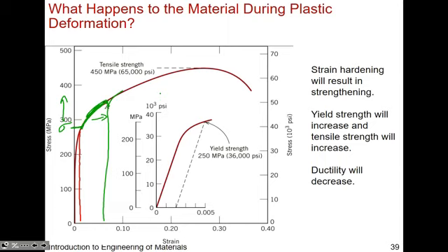But in the example that Nathan asked about, when you're rolling a material, you are changing the grain size per se. That's one mechanism. Another mechanism is to heat a material, to change the rate of solidification, to change the grain size. That is something we'll talk about in chapter 10. I wouldn't say that there's a significant amount of grain size changing just based on this example.